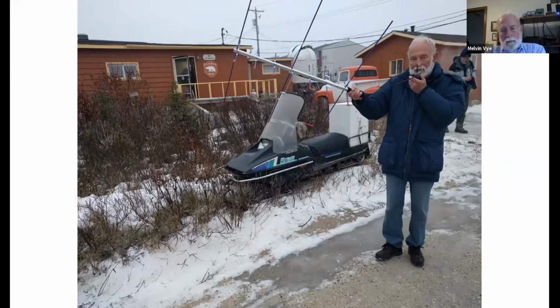But how do you handle Doppler? Now we're on FM, and most of the satellites now are mode UV. That means I transmit on UHF and receive on VHF, which in a way is kind of unfortunate. There was a real workhorse satellite that the Saudis put up, SO50, which transmitted VU. And that was a lot handier because if you transmit on VHF, you don't really have to worry about Doppler, because the Doppler is not going to shift more than 3 kilohertz. And 3 kilohertz on FM is not a problem. But it's going to shift about 9 kilohertz on UHF, and that is a problem.